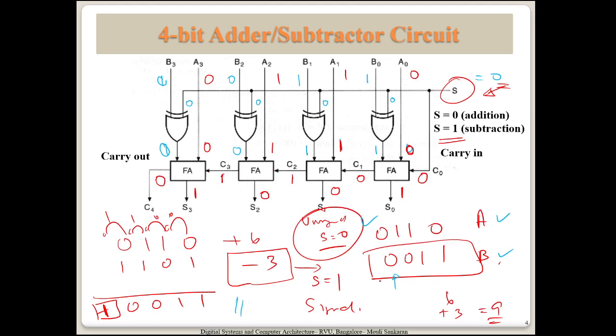Now if you perform a simple plus arithmetic, because we are adding 6 and 3 now, this will be 1 and this is 0. This is what is shown here, this carry and this is carry, and this is 0 and 1. So the result is 9 and the carry is 0 here. What has come out of this addition is 0 here. So 9 is the correct value, because 0 carry means that the unsigned arithmetic is correct. So plus 9 is the answer.